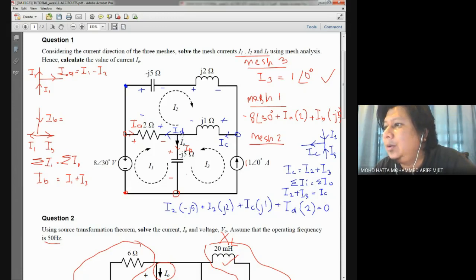The way I get the equation of ID is by looking at this point. Why am I not looking at this point? Because this point is quite cramped. We have a current over here, which is IB, and IB also is a combination of currents. And the current over here is IC, also a combination of another current. Maybe the best way is to find the junction that definitely tells us the exact current flowing through there, not the combination of two currents or maybe more. Luckily, at this junction,